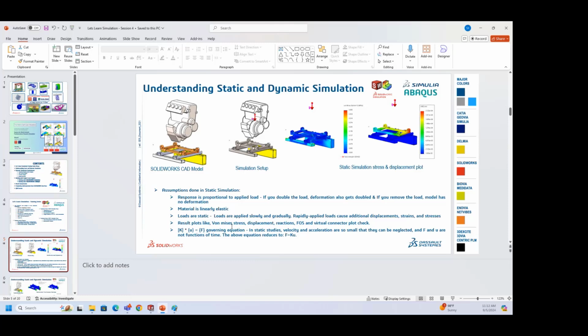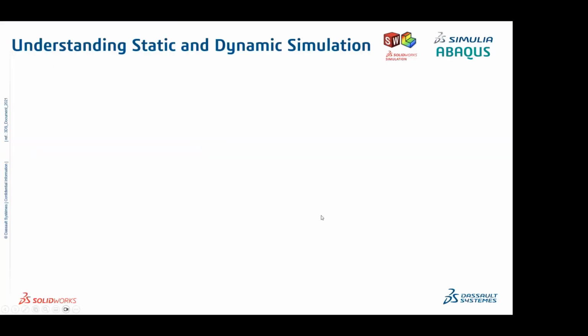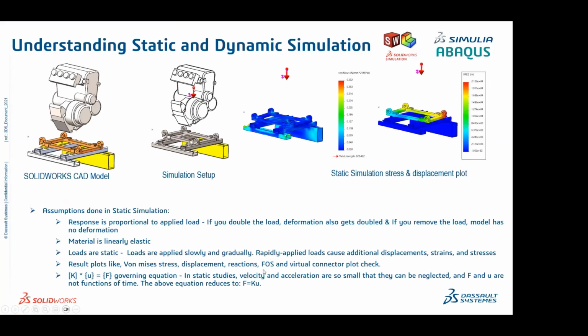And finally the engineer is going to evaluate the factor of safety, how safe the design I have done is, and whether it is over designed. If it is over designed, in the same environment you will change certain dimensions, or the geometry, or the material, and then rerun the simulation to get a more optimized solution.